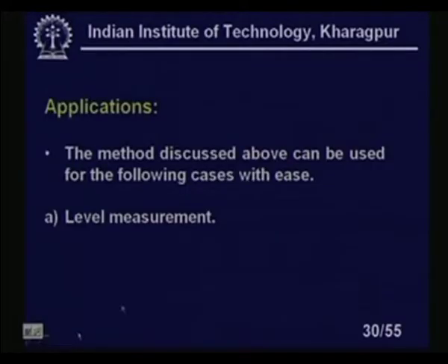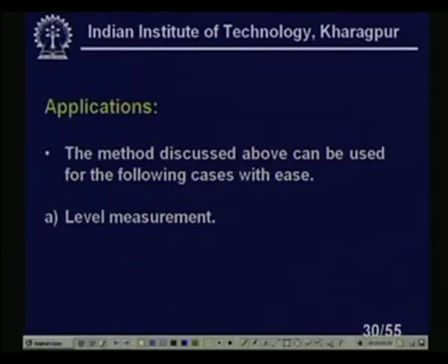You cannot use both the Bourdon gauge and the C type Bourdon tube; you have to use either one. You use bellows, because the bellows will try to expand, so that if you connect an indicator, it will show you the level, or if you connect it to a Bourdon gauge, there is a deflection of the free end of the C tube.